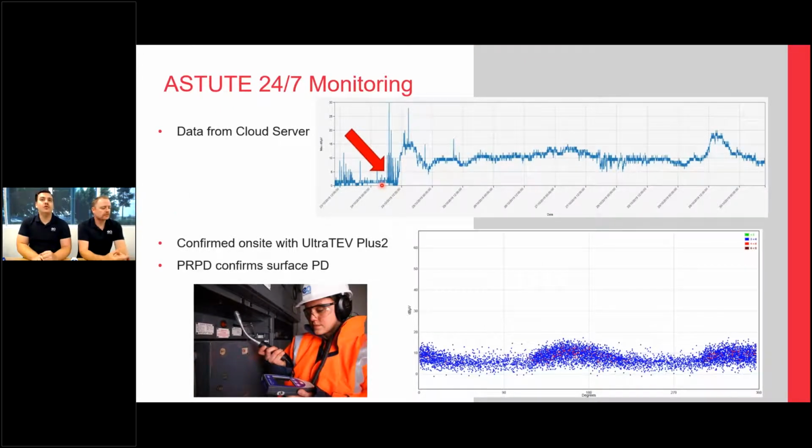So you can see normally down here, you're reading between 0 and 3 decibel microvolts. Then suddenly there was an increase, it spiked up and then plateaued at about 10 dB microvolts. This is an average sample reading over a 2-minute period, so it's very consistent. When this event happened, it triggered an alarm event.